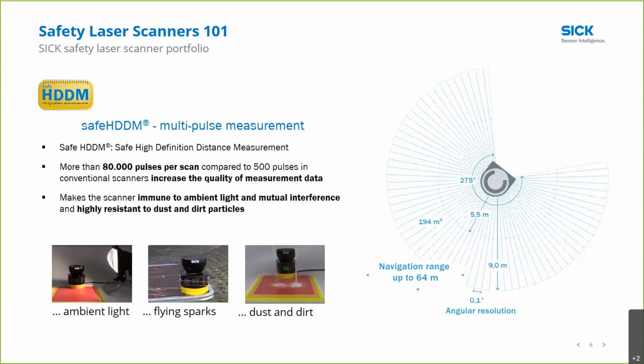And so right off the bat, I want to make it clear that SICK has done everything possible and has done a very good job to try to eliminate those inherently from the get-go by using a very highly technological scanning principle. So ambient light is something that we really see is not a problem at all with these scanners. The dazzling error is more or less eliminated completely. So we're able to deal with up to 40,000 lux of light.